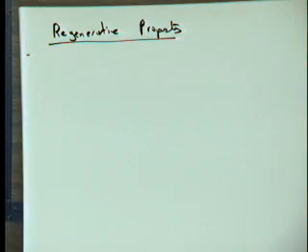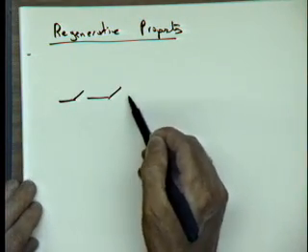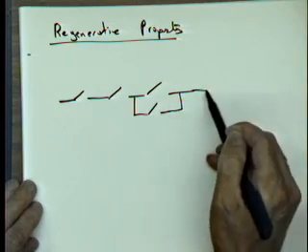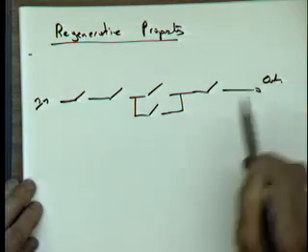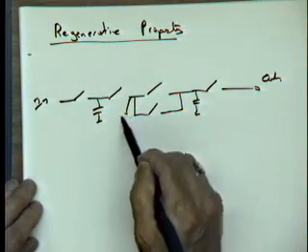Let's say, suppose that I would implement logic using just switches. Just an example, right? I can have a network, and I put some in parallel and some in series, and so on and so forth. And this is my input, and this is my output. So you have capacitors on every intermediate node.